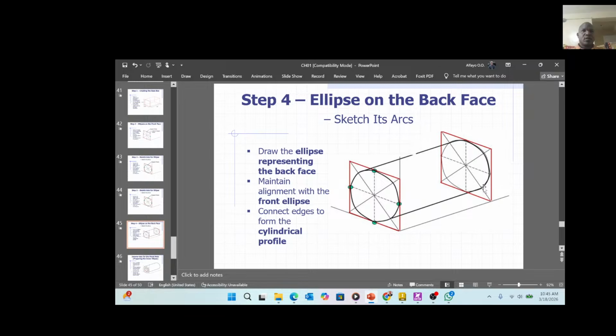These hands-on skills. You don't need to come here and draw the same. Initially, as a beginner, you can do the same, but you can transfer this to the back end after measuring 100 millimeters and the 100 millimeters from this point. At this point is where you can just draw this isometric cube, hypothetically, and draw the diagonals in the same manner and also trace the same. You can easily now trace this curve.